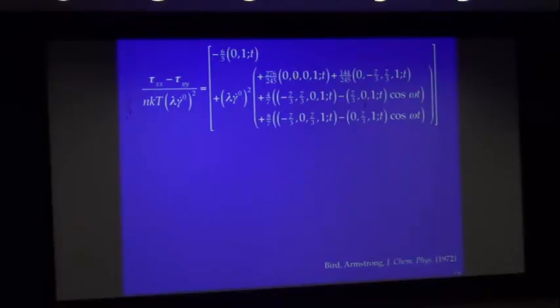I said to Bob, how did that happen? Well, here's the cool thing about orientation. Some parts are contributing to the shear stress, some parts are contributing to the normal stresses. You see, some molecular motions are giving rise to the normal stresses that are not contributing to the shear stresses at all, and it turns out you have to do more work on the orientation distribution function than you had to do for the shear stresses here.